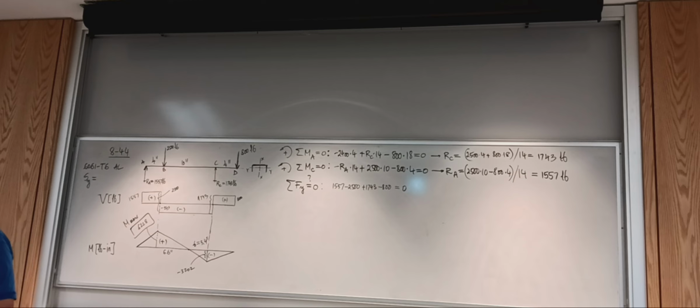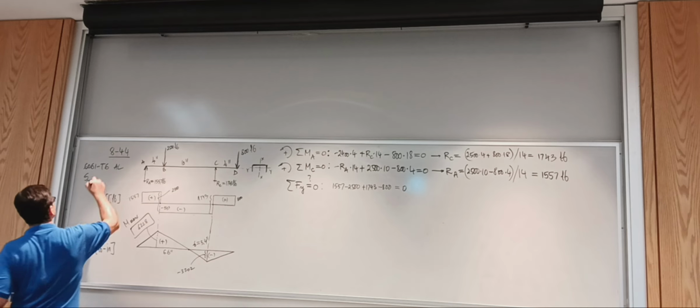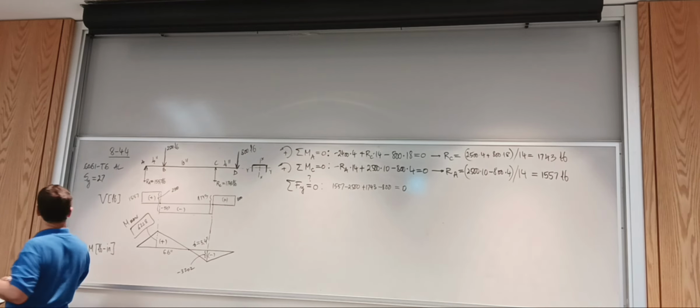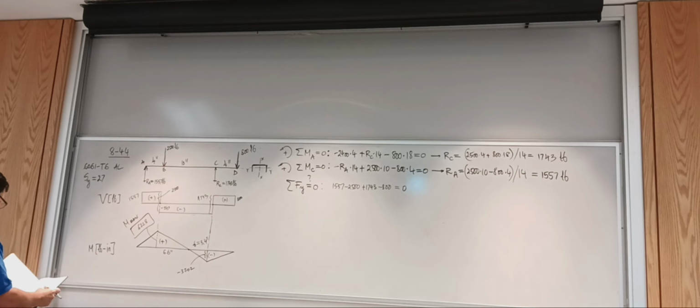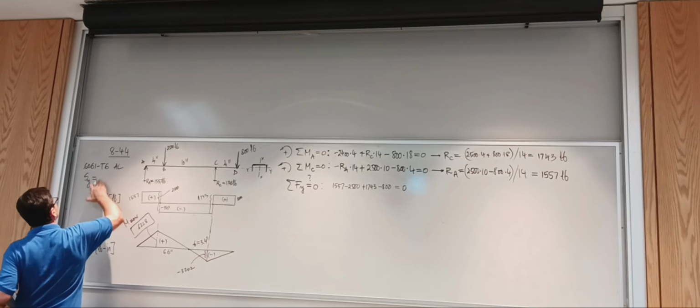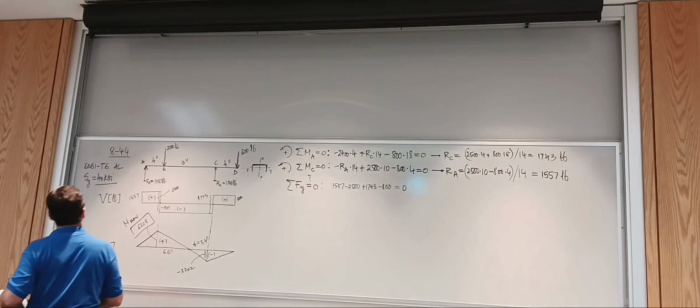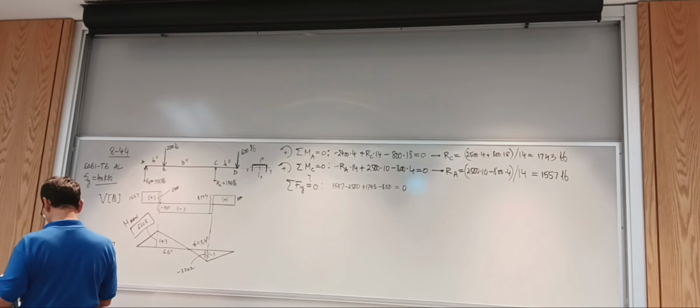Yield strength in shear for this 6061 T6 is 276 megapascals. Oh, I'm looking at the problem working in PSI. Okay, yeah, no problem. So we need the KSI value. That's 40 KSI. Okay. Anything else? No, this is what we need from here.